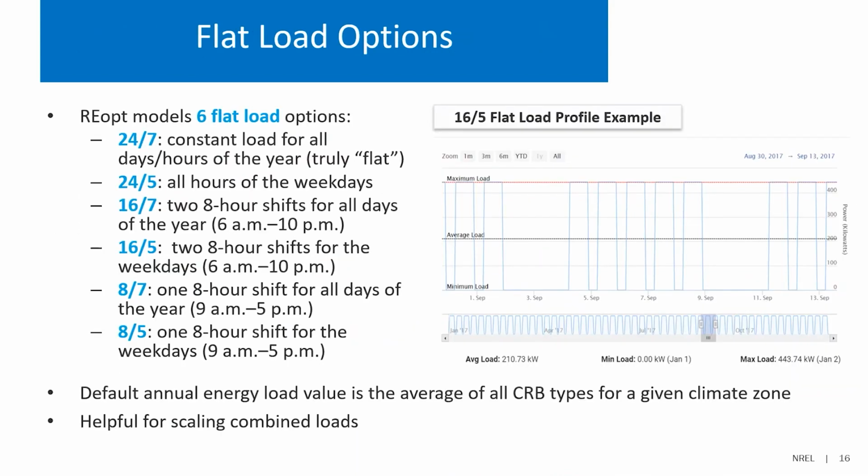And continuing with additional modeled load profiles, we also have these flat load options. So these are just constant loads, and we have 6 of these, depending on which hours of the year the load is active. So for example, the 24/7 profile is the truly flat constant load across all hours of the year. 24/5 is all hours of the weekday has a constant load. And then 16/7 is just a flat load from 6 a.m. to 10 p.m. every single day.